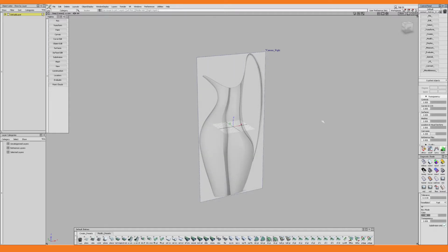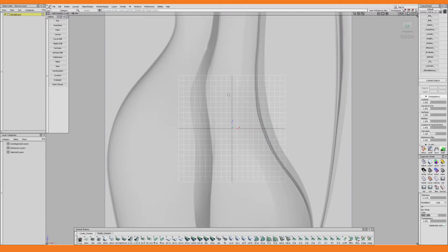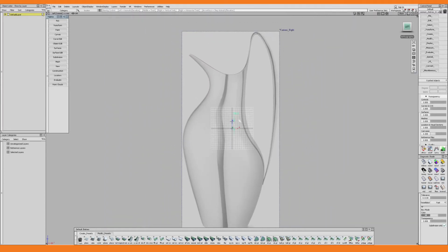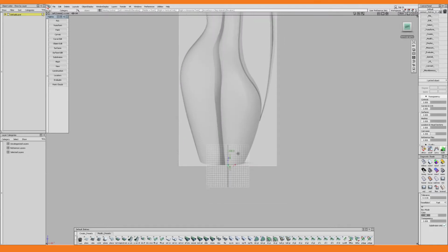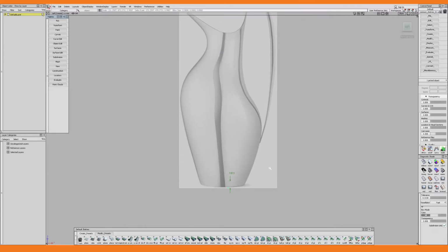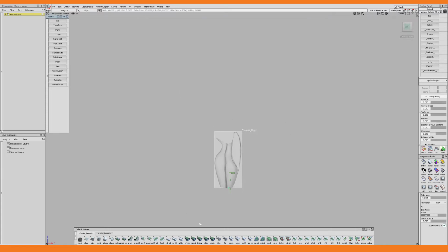The height of this 1.9 liter picture is 330 millimeters, so I create a distance locator with that same height. I snap the start point to the center and then I go up here to the command input where I type 0, 0 and 330, and this gives me the distance locator. I then snap the pivot to the bottom of the canvas image before I move it into place. And now I can hide the grid and scale it accordingly.